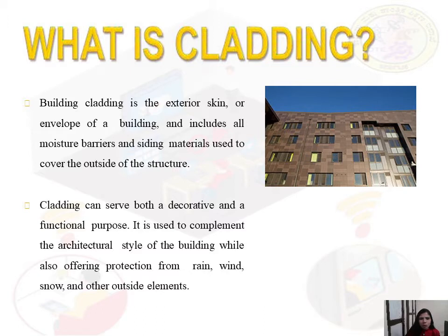However, properly designed joints with sealant can completely keep out rain infiltration. If the cladding is not properly designed and the joints are not completely sealed, what will happen? The rainwater can enter the building through the improper design or the loose, leaky joints.